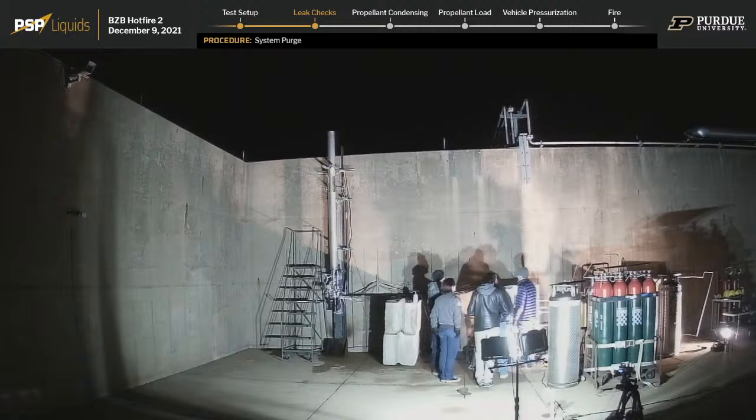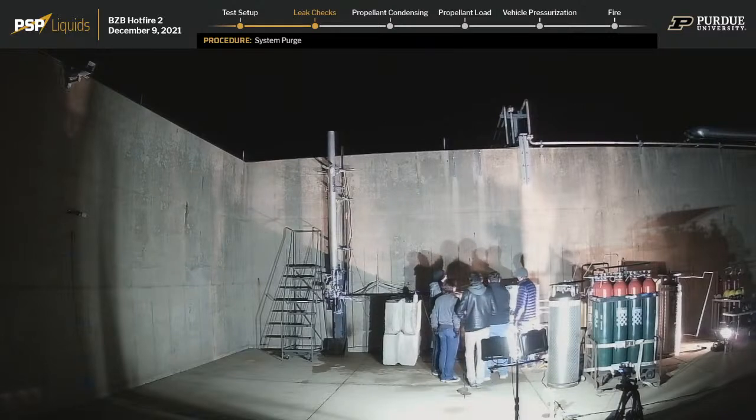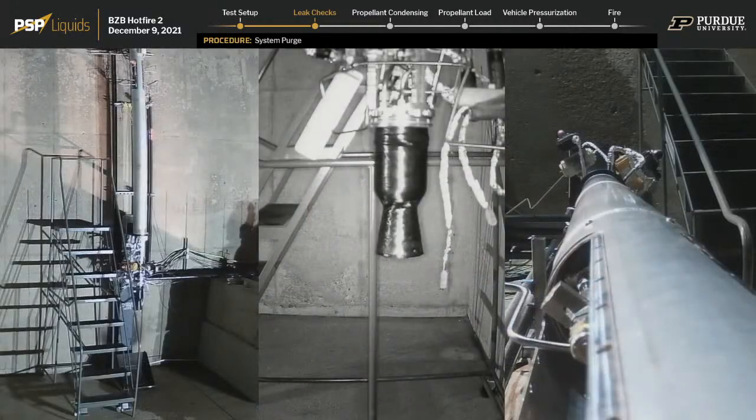You just heard her call out the fin can purge. So this is using the PS Piccolo, as we have deemed it, to blow inert nitrogen into the lower airframe. MRN201 is loaded to 150 psi. This will mitigate the risk of fires in the lower airframe.